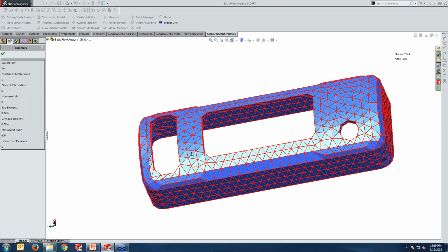The best case is if we have a fully symmetrical triangle, L1 equals L2 equals L3. So that is the main thing. If you can achieve that, your aspect ratio is exactly 1, and this is the perfect element. But if you have something around 9, meaning one length is 9 times bigger than the other one,